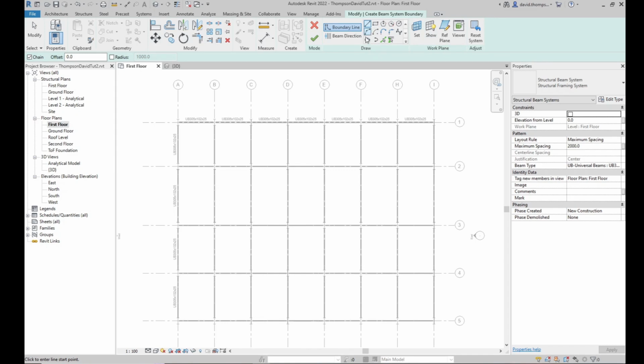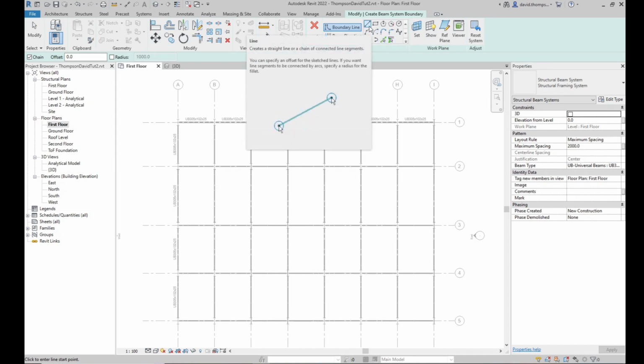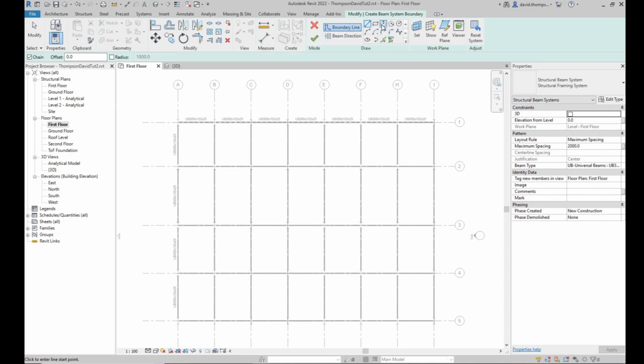So we see a little section here in the Draw panel. There are different options here. If you hover over them, don't click anything yet. We can click lines and all this. This is basically how it's going to help us place the beams. But we're actually just going to use the rectangle option because we want to place beams in these squares. The rectangle option is the easy way to do it. Otherwise you do individual lines, which would be a waste of time and effort.